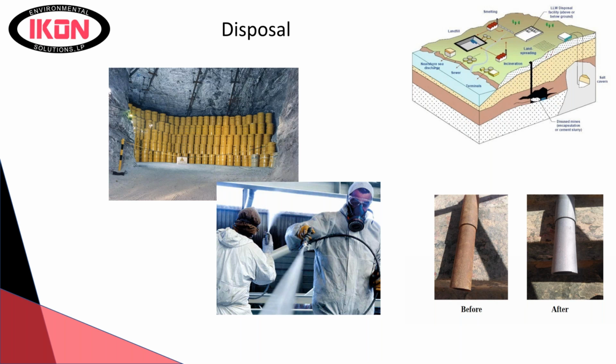Do we follow the TCEQ waste classification guide to classify NORM, or do we follow somebody else's classification guide? Again, you have options. If you can classify it as E&P waste, exploration and production, then you can follow some of the Railroad Commission rules, and you can send that to an injection well.